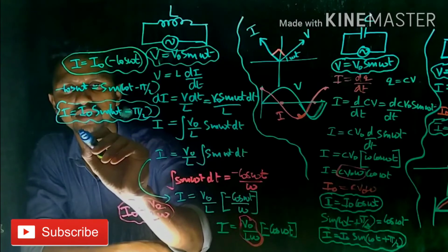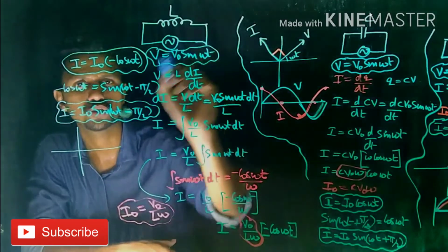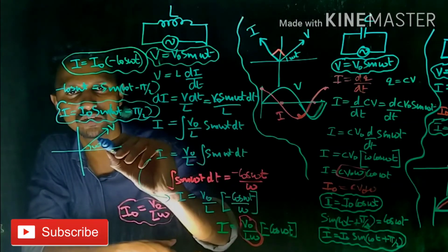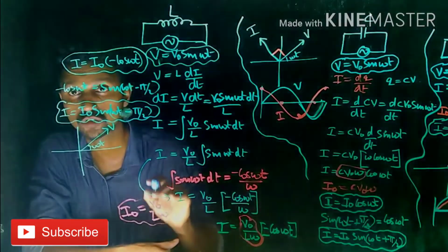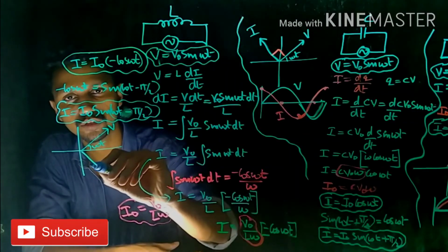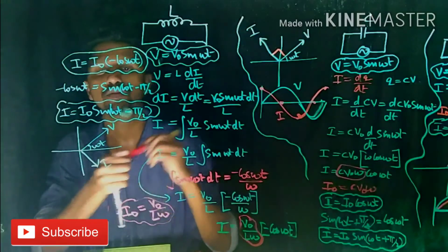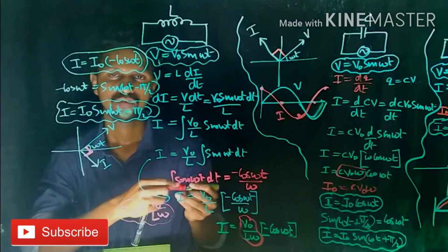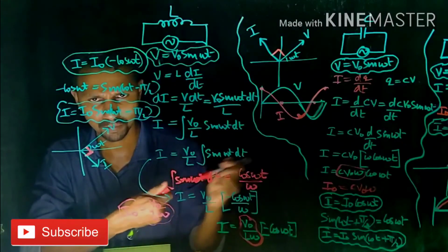On drawing the phasor diagram, we mark the axis initially. Then let's draw the voltage phasor. This is our voltage phasor. This angle is omega t. And in this case, the current is lagging. Since the phasor is rotating in the anti-clockwise direction, current lagging means the current should be drawn over here. This is the current, and the angle between voltage and current is 90 degrees. From this phasor diagram, it's clear that the current is lagging by an angle of pi by 2.